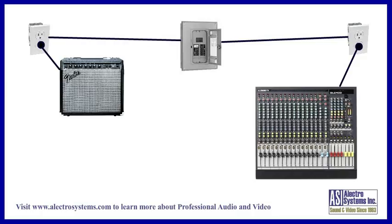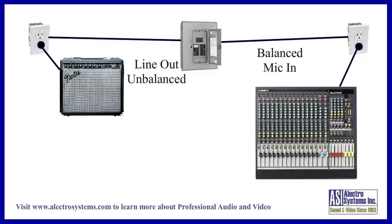Using the guitar amplifier as our example, when connecting it to the mixer, we need to do two things to the signal. We are coming from the preamp output of the amplifier to a microphone input on the mixer. Because the amplifier output signal is line level in the neighborhood of up to a volt or more, and the microphone input on the mixer is expecting only a few fractions of a volt, we need to significantly reduce the amplifier signal before it gets to the mixer. Also, the amplifier output is unbalanced, so we need to convert it to balanced because the microphone input is balanced.